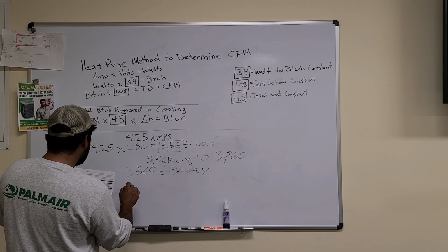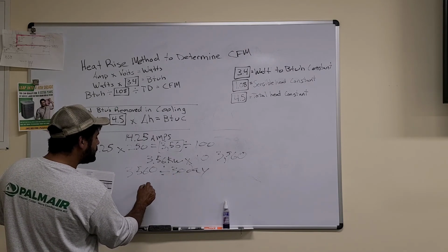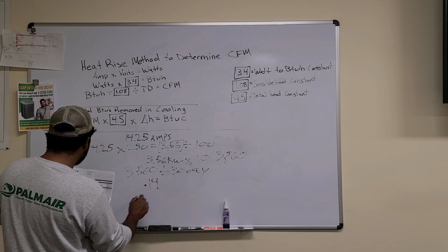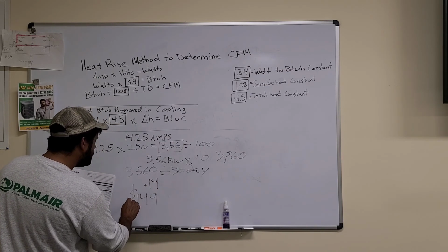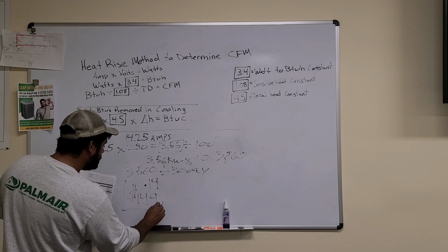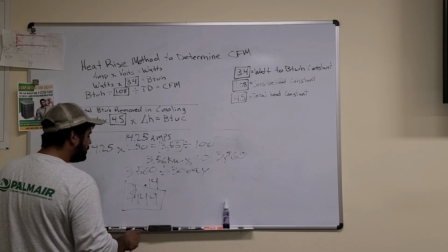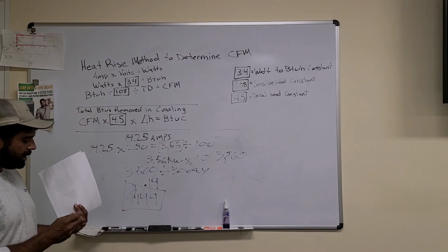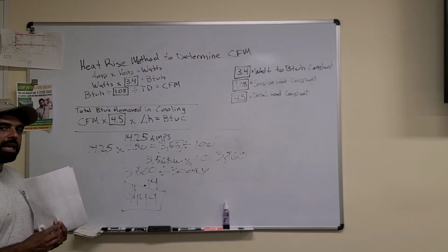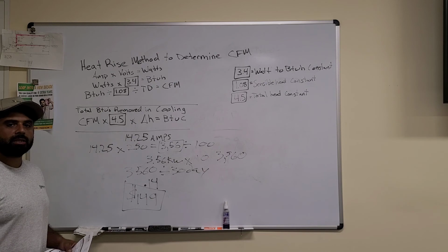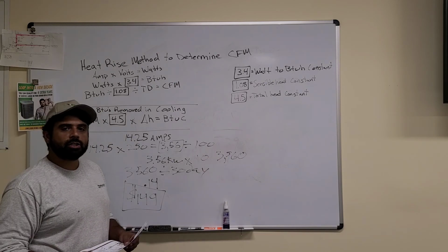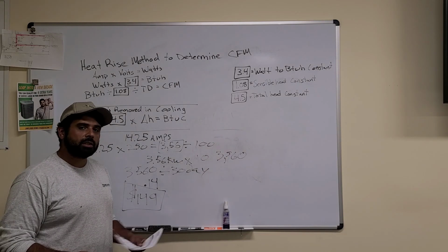If we take that and multiply it by the average electricity cost, which is about 14 cents, we're going to come out with $149 for the month. This 4-ton air conditioning system, running 10 hours a day for 30 days in a row, is going to cost them about $150 a month. Again, guys, a real easy way to show a customer what it's actually costing them per month.